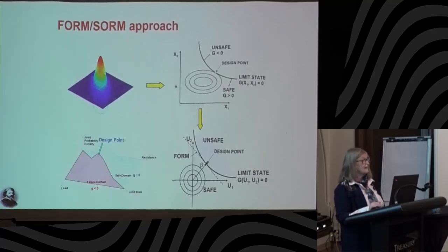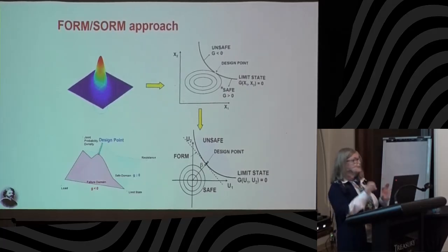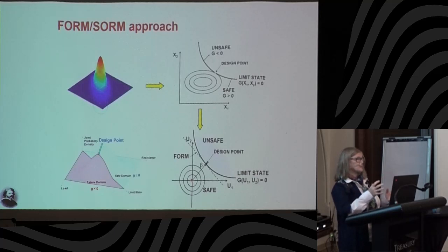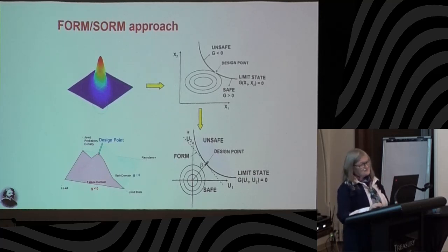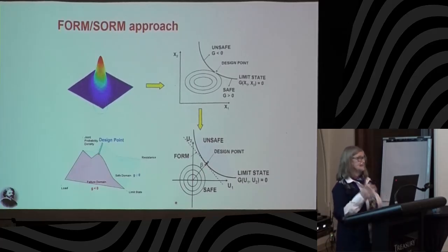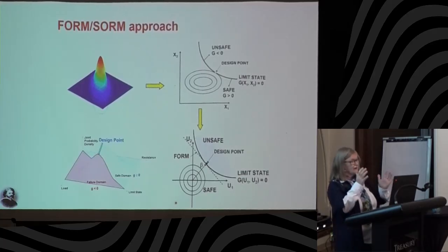What we do is the analysis and find the distribution of safety factor for all the variation of the random parameters, and you define a zone which is unsafe, where safety factor is less than 1, and then the region that is safe. Through statistics you do a transformation of this into a normal distribution, and then theoretically, lo and behold, the distance between the unsafe and safe design is called the reliability index and is related to the probability of failure. Easy to calculate because of normal distribution. But you don't have to go into the details because that's a black box.